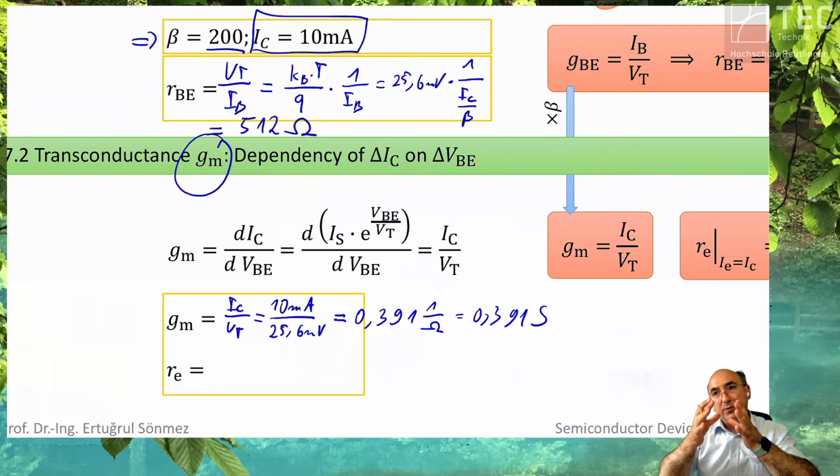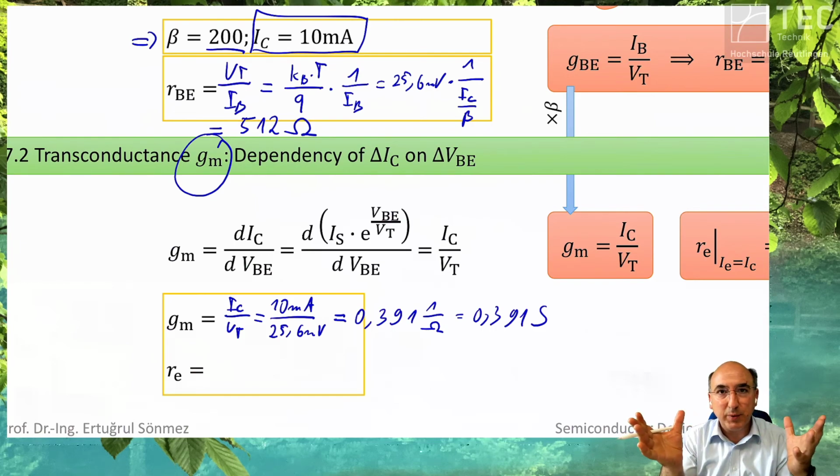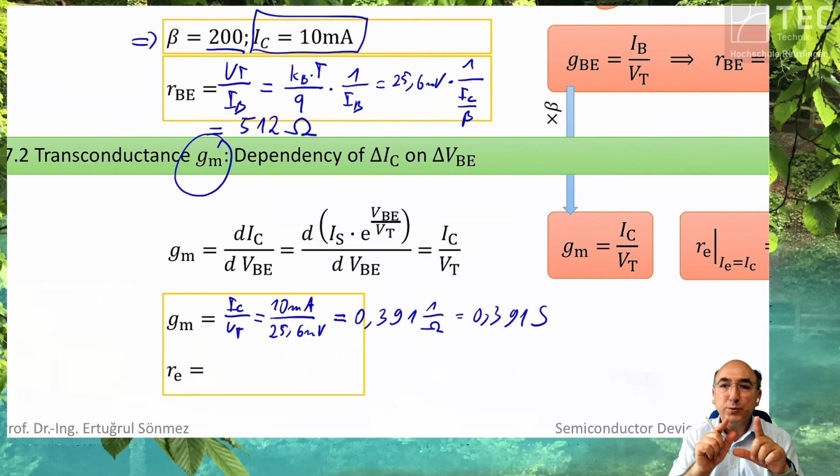But with transistors in MOSFET technology getting smaller and making more complex circuits possible, you can even generate 2 gigahertz amplifiers using MOSFET technology. But this is only possible with highly sophisticated, large scale, small transistors like those made by Intel, AMD, TSMC. But at the beginning, your feature width was 1, 2 micrometer. And with 1, 2 micrometer feature width, you made several gigahertz bipolar transistors and 1-digit megahertz MOSFETs. That means at the beginning, the gigahertz range was only reachable by bipolars. So bipolars are also cheaper for the same frequency application.